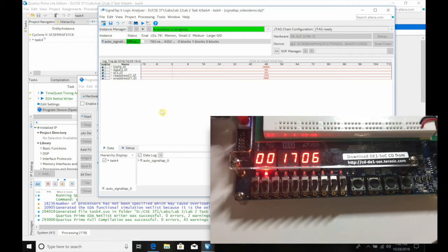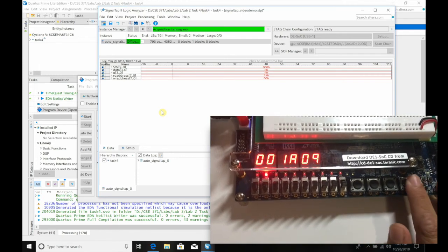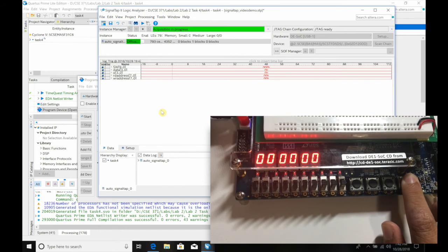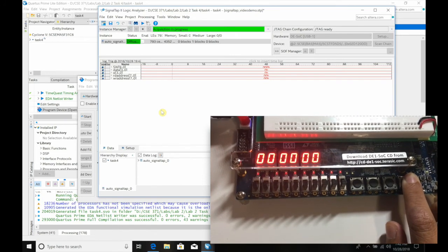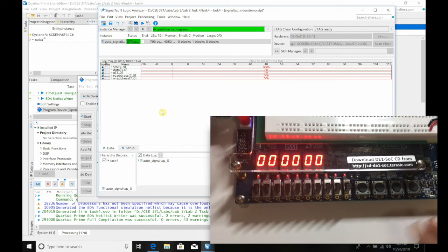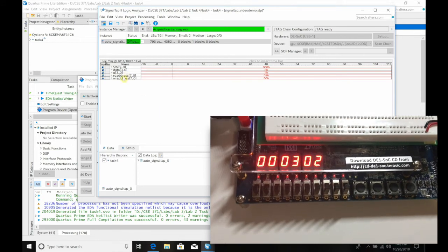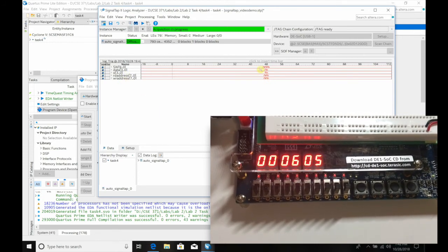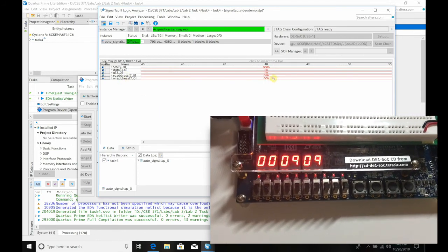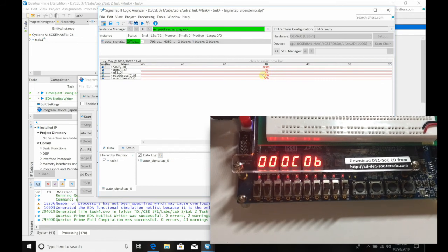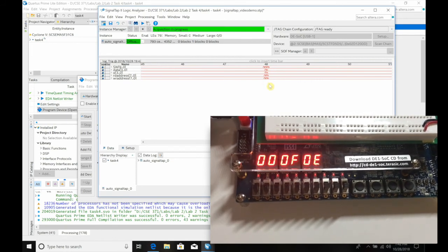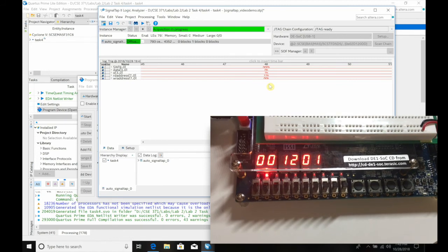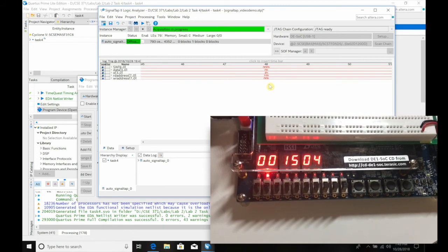So now it's just cycling through. And so I'm going to restart it so we can look at the SignalTap and also the FPGA. Once it reaches a read address of 8, we should know that there should be a 9, which is right there. It goes pretty quick, but if you replay the video, there will be a 9 in the Q.